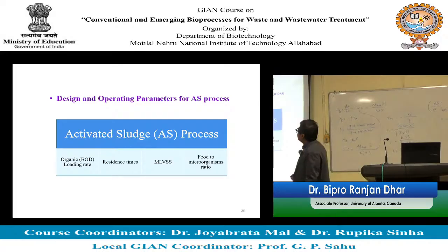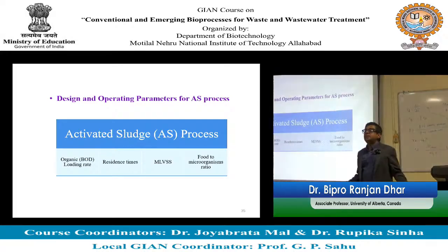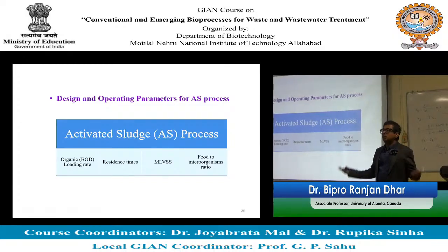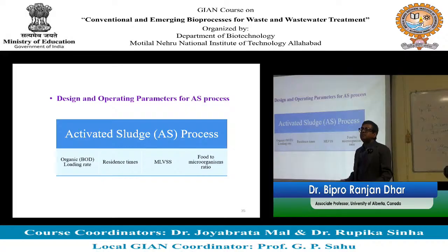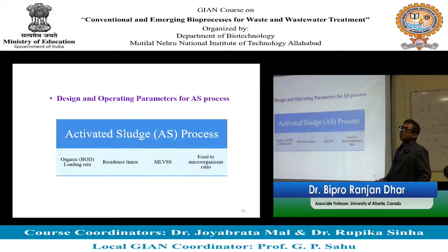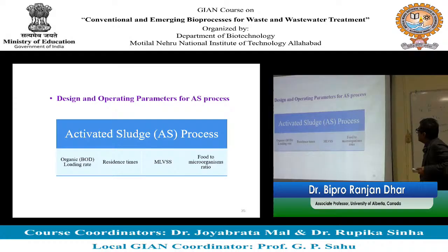Residence time. Microbes need a specific amount of time because they want to grow. If you don't provide them enough time, they are going to leave the system before they can grow, right? So we need to provide them enough time. There should be enough time for microbes to be in contact with the contaminants and actually remove them, right? So the residence time is another important thing.